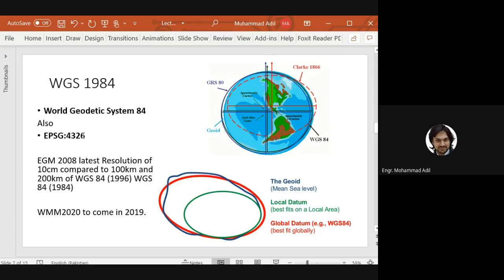So commonly, it is known as World Geodetic System 1984 data, and we will be using this WGS 84, which is also known as EPSG 4326, for our future maps. Whenever we draw them, we'll use them. And otherwise, if they are downloaded maps with EPSG 3857, we will convert them into EPSG 4326 because our points that we get from our GPS devices in our mobile phones are on the 4326 system.